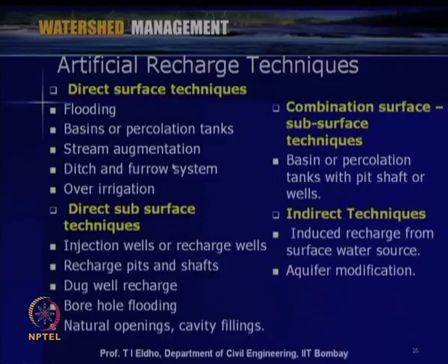These are some of the artificial recharge techniques which we can utilize to improve the percolation or recharge to the aquifer system, so that when surplus surface water is there, it can be recharged to the aquifer system and used later when scarcity is there. We will have a more detailed discussion about artificial recharge techniques in later lectures.